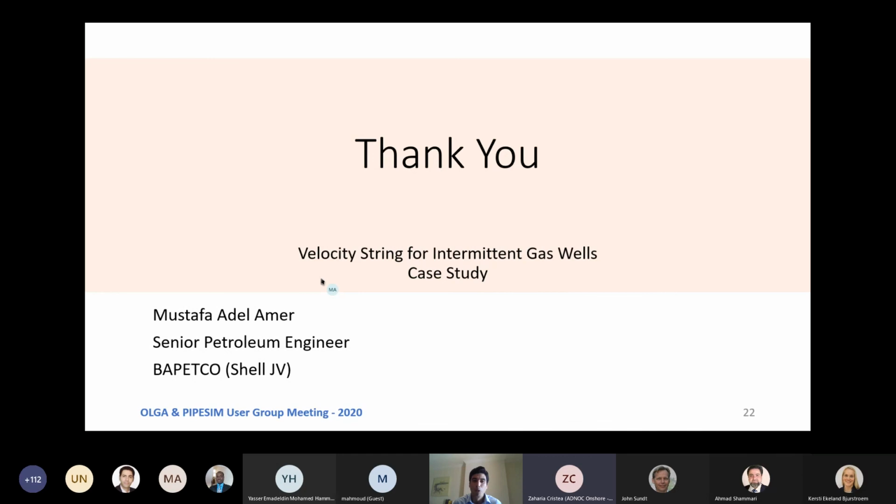No, because it's already isolated. What they have done during the operation is that we tested it with, I think, 1,000 psi surface pressure for 15 minutes, and it was okay. And we even proposed it for fixing integrity failures in existing completions, a pinhole in the area between the packer and the subsurface safety valve.